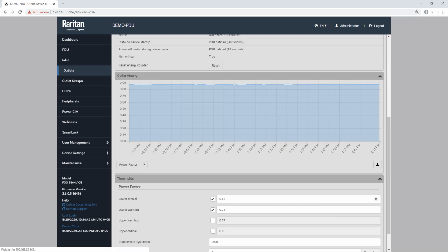Once the power supply of your server is in an idle state and it's not consuming 75 watts of power, some feedback that we've learned over support cases through the years and through engineering research is they're not required to use that power factor correction circuit when you're below that level of consumption. So your power factor is going to dip down when you get below a certain point of consumption, and therefore you're probably going to cross this threshold at some point if your servers aren't doing work.